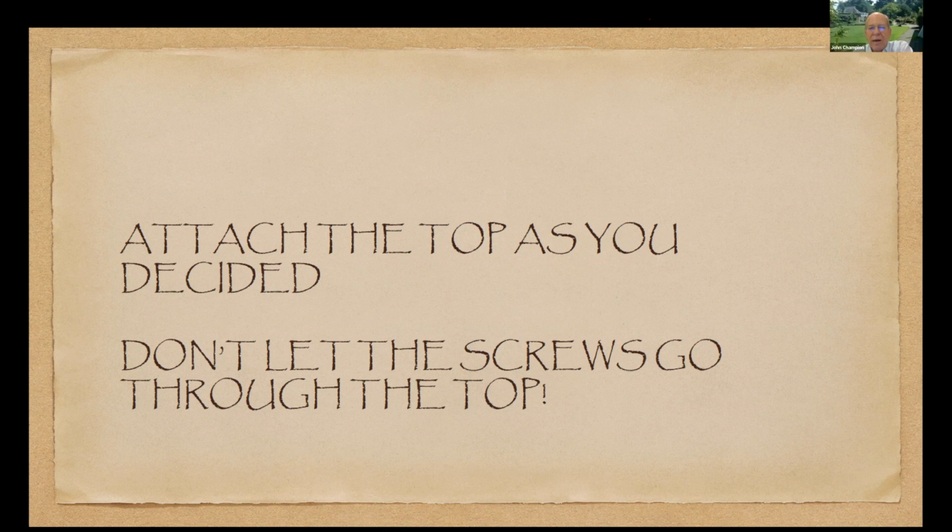Someone was asking about putting polyurethane over an oil finish, which their recollection is it usually doesn't work well, but you're putting a polyurethane over a boiled linseed oil finish. Obviously, you've never had an issue with that in your experience. I've never had an issue, and my understanding is that many of the polyurethane type finishes have linseed oil type oils in them anyway.